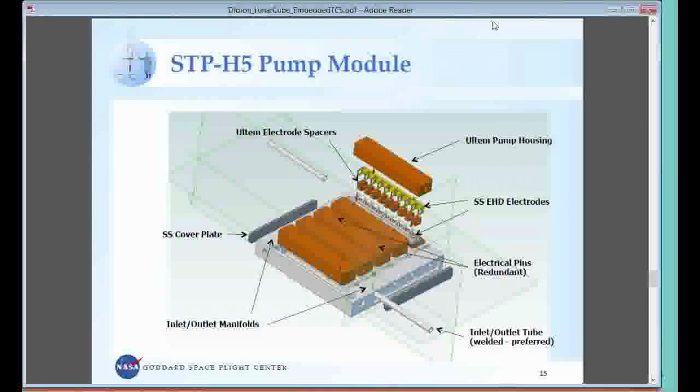Can you give the 2-sentence contrast between this technology and things like heat pipes? Yeah, heat pipes are a capillary phenomenon, so that has that limitation. Actually, I view them as complementary. This is electric field-based phenomena. We use electric fields to pump fluids, but we can also manage fluids with that. The pumping of the fluid is electrophoretic. The management of the fluid, in other words, putting liquid and vapor where you want, is the use of the dielectrophoretic force. So in some designs, you might use them both. Oh, I anticipate that. Okay.